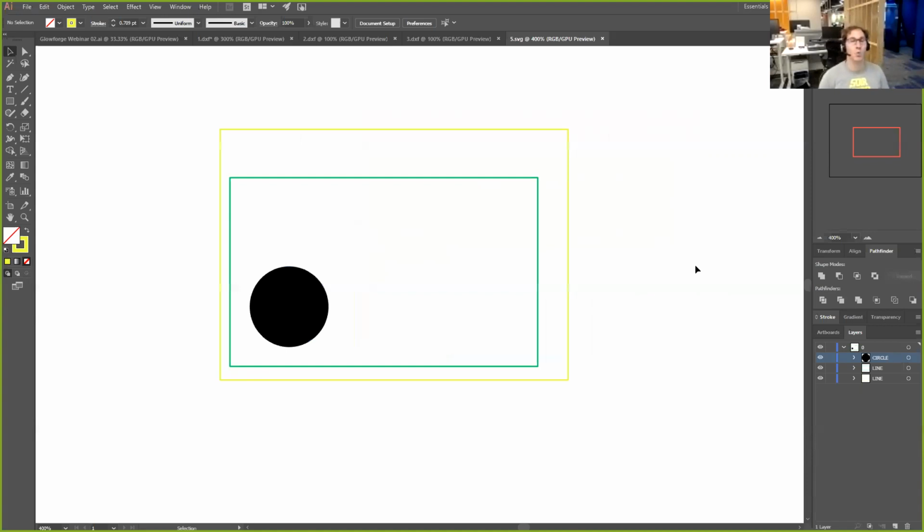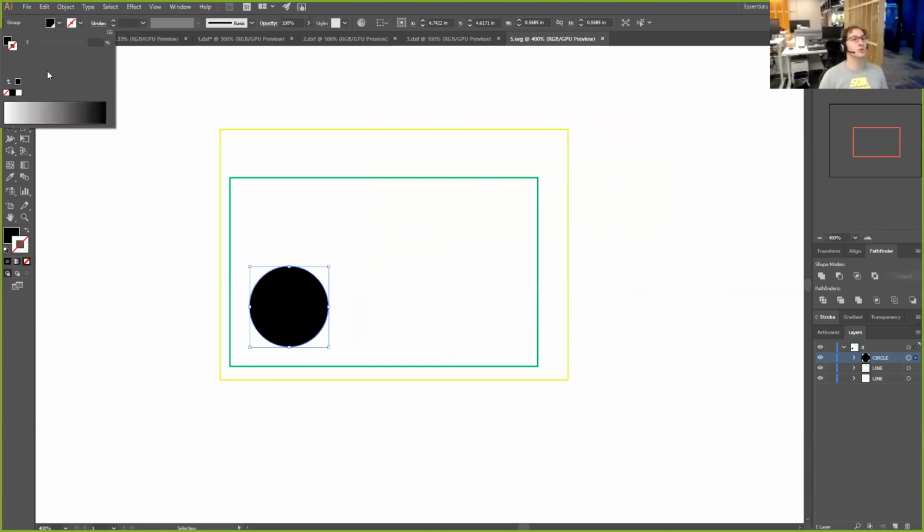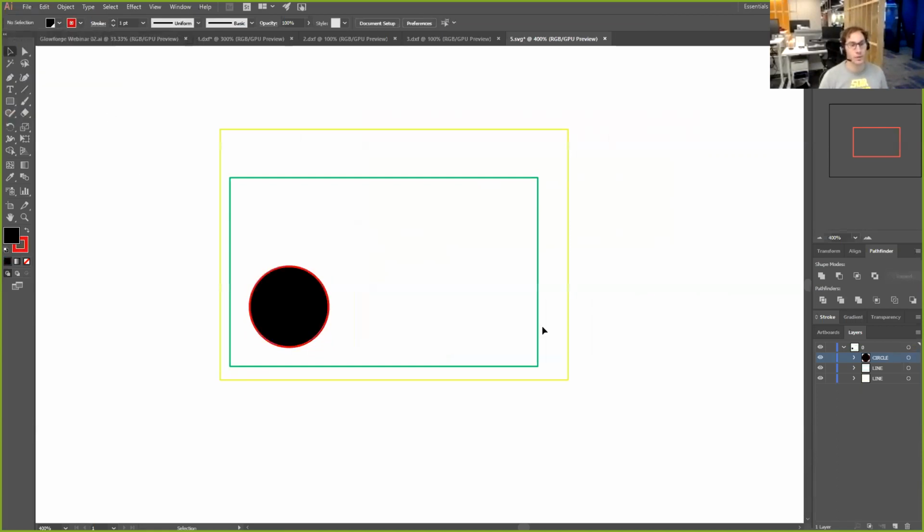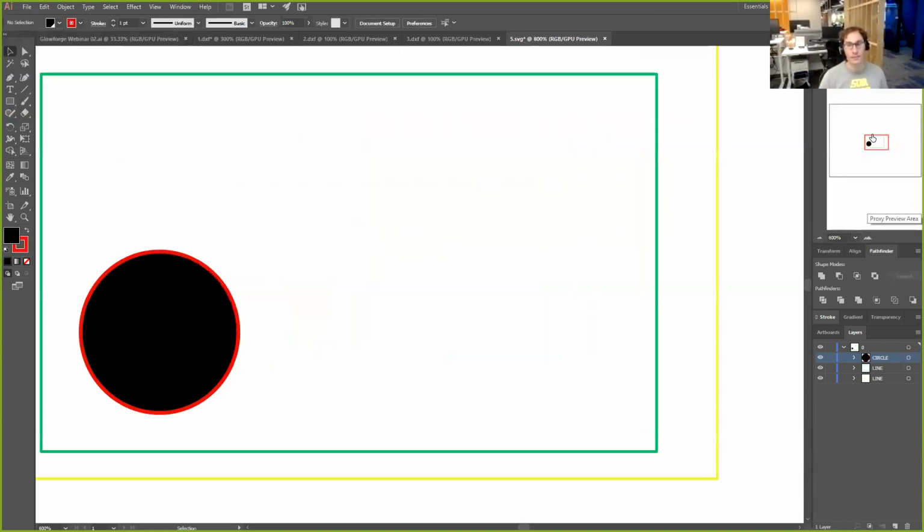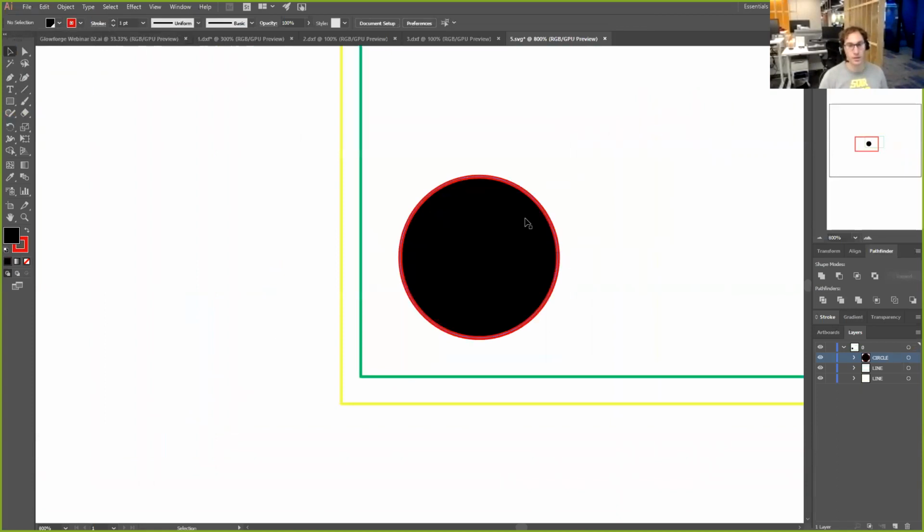All right. One note of warning that I found out the hard way, and then also was taught by the Glowforge community. If you want to set, let's say, this circle to be both an engrave or raster in the center and a score on the outside, if you select a color for the score as well, it doesn't matter what you pick, but the Glowforge app is not going to be able to determine that this is two different things in one.